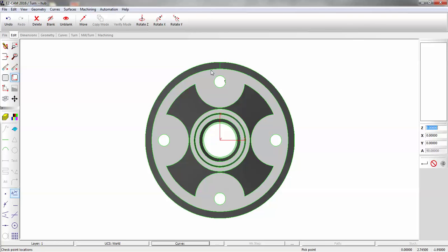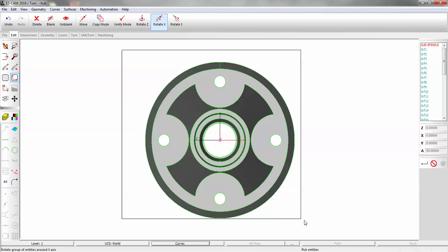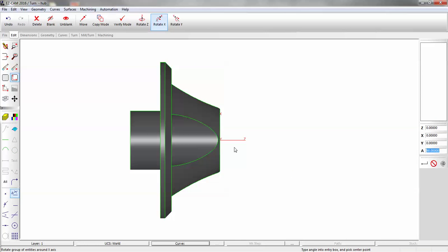So now I need to just simply rotate the part 90 degrees. Select our surfaces in geometry. The next thing you would do is create a path for the tool to follow. And if I was to do that here, we would be catching the surfaces instead of getting the tapered angle.